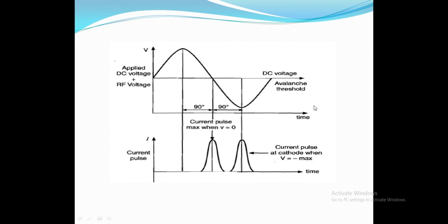The increased velocity of the electrons and holes results in additional electrons and holes by knocking them out of the crystal structure, which is called impact ionization. The process continues, creating additional carriers at the junction, and it now snowballs into the avalanche. If the initial field was at the threshold of allowing this, the avalanche is not instantaneous; the whole process takes a time.